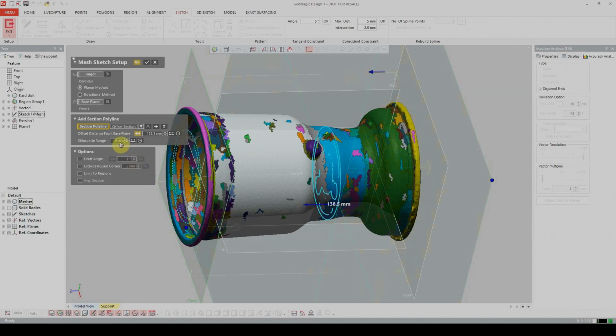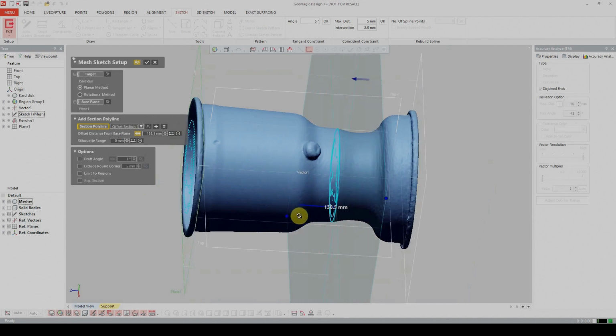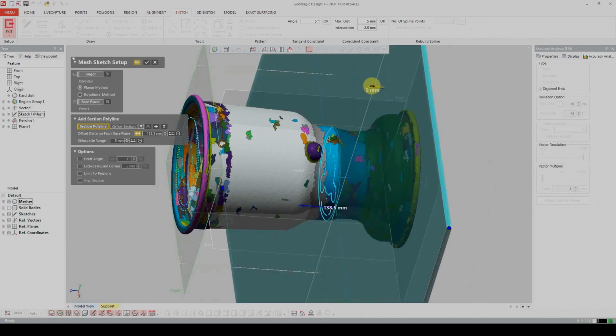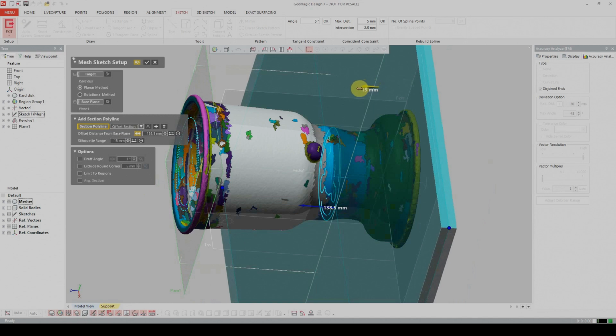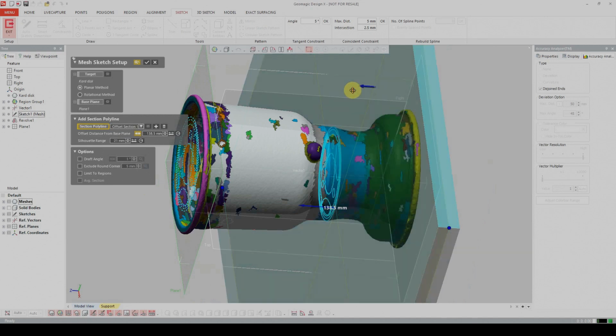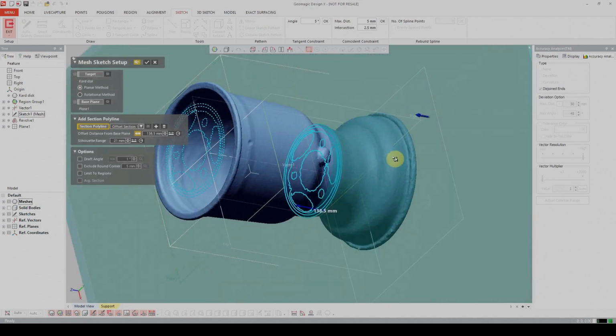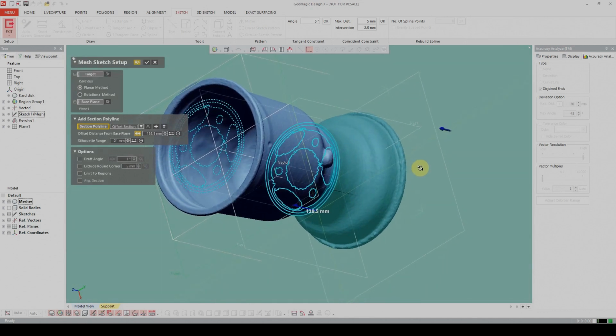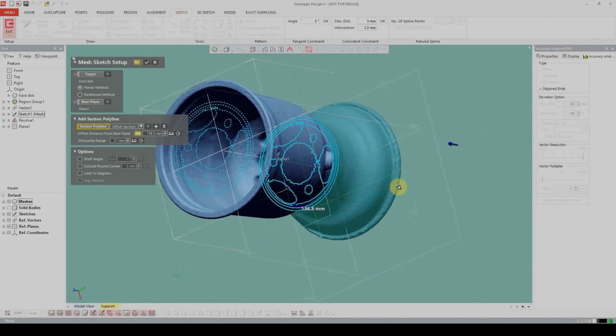And then I'm going to get even more information about holes by selecting Silhouette Range by dragging the smaller arrow, so that most lines will pop up in my sketch. And you might remember that the Silhouette tool is cutting the part with many planes, not just one plane. And that is why more lines appear in the sketch. Then I'm hitting the OK button.